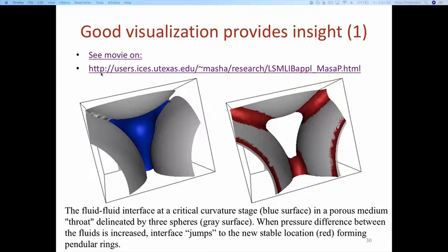And what's left are these pendular rings around sphere contacts. If I had some water in between my fingers, I would see a pendular ring, right? Those of you with water bottles can try. So this is essentially my water here next to the contact of 2 spheres. This would be my irreducible water in soil, or any kind of granular medium. And typically this water is not going to move. It might evaporate, but I can't displace it.